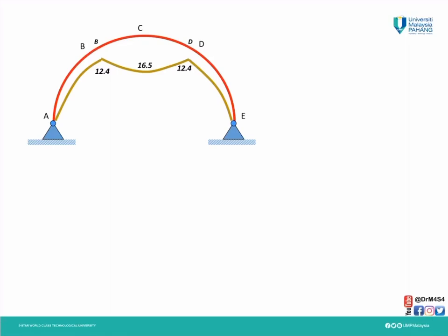To calculate the bending moment at B, we take summation of moment at B equal to 0, positive clockwise. Remember our cross section we cut at point B before. And also we know our y is x minus x squared divided by 20.